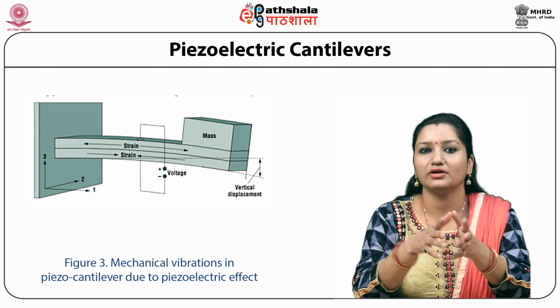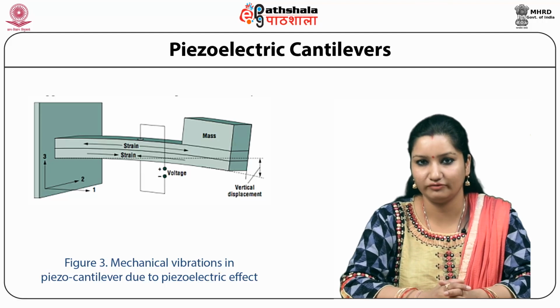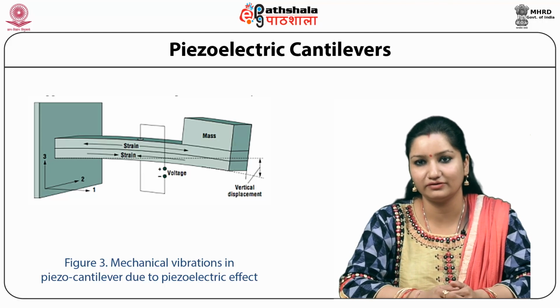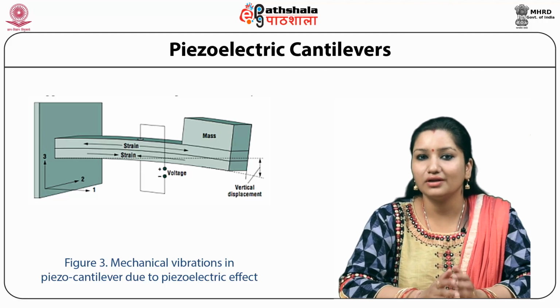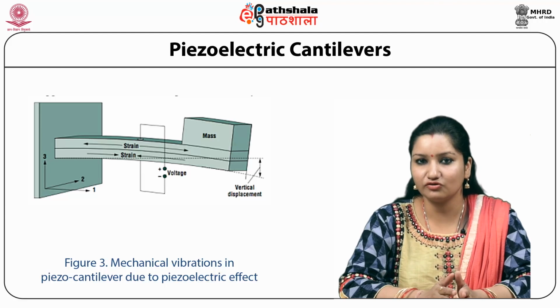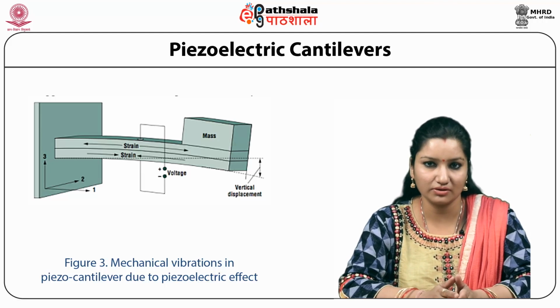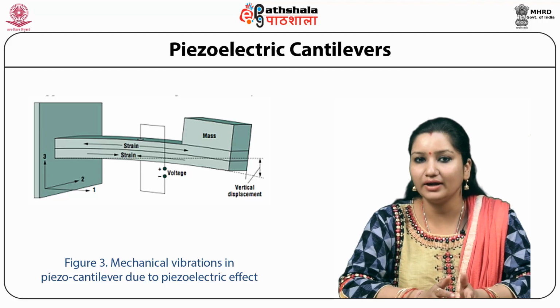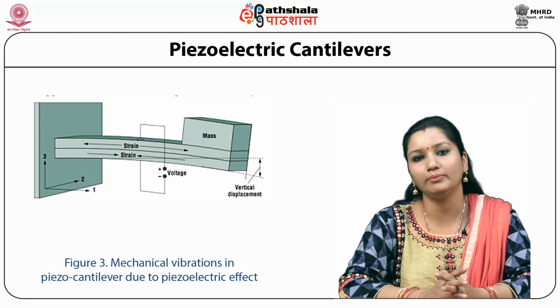This lowers the resonant frequency of the beam and increases the deflection of the beam as it vibrates. The larger deflection leads to more stress, strain, and consequently a higher output voltage and power. Hence, by adding the variable proof mass, the resonance frequency of the cantilever can be tuned.